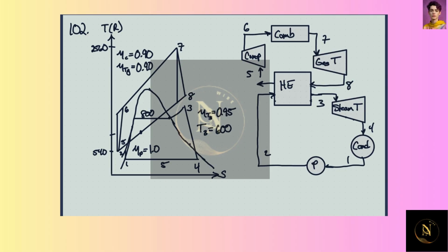So let's see here. What are we saying? The pressure in the heating system where the steam is now condensed will have to be increased to 10 psia. I did not change the thing that needed to be changed here, so that should be 10. That's really the only thing that changed, other than that we're now using the heat coming out of here for something. So the utilization factor would increase because we're now utilizing that. Everything else is the same.